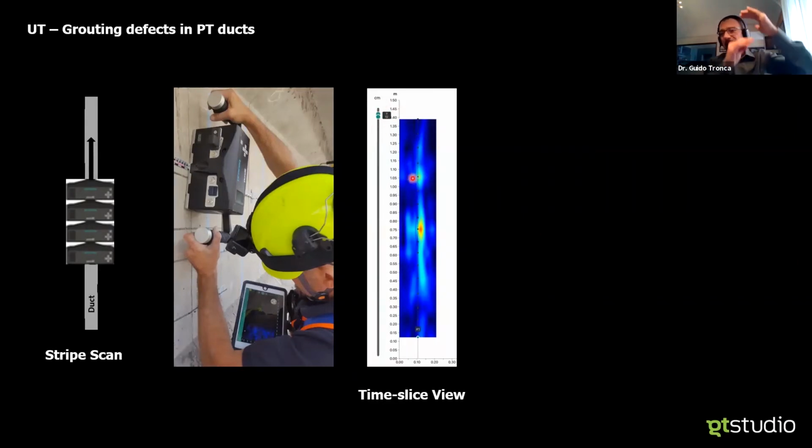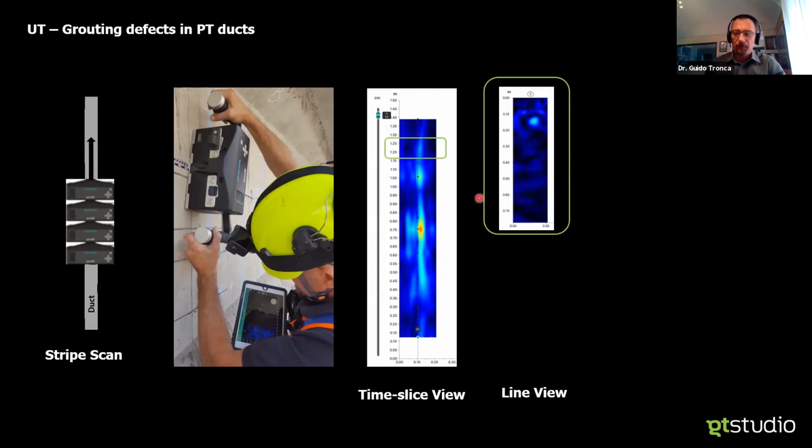What depth? The depth where the duct is. I see this distance here, which is the same distance that I read here, versus a given depth, and I see that I have a duct at around 12 cm.